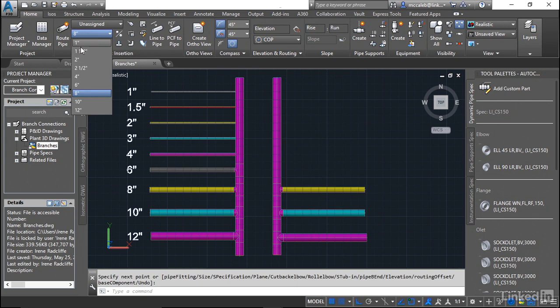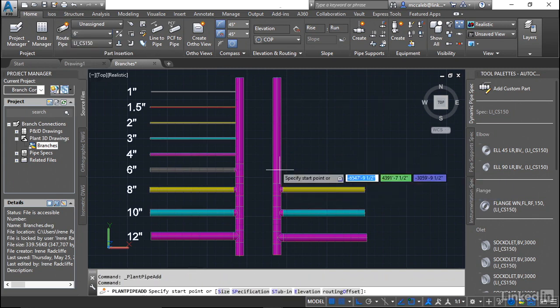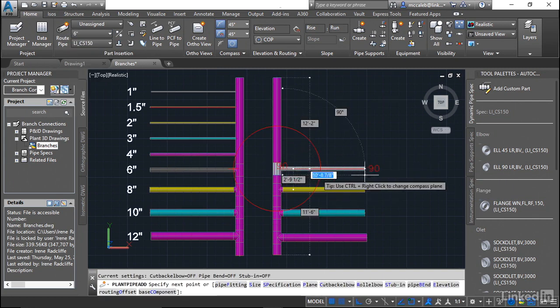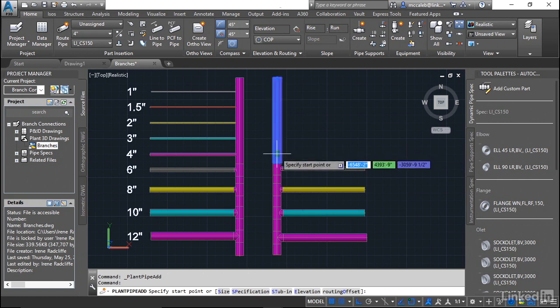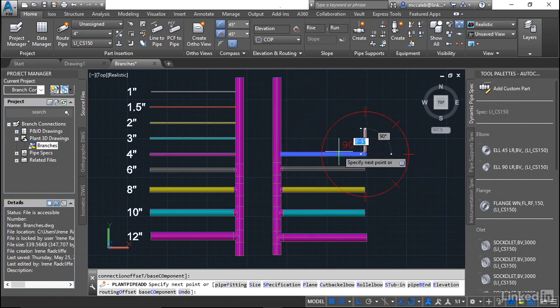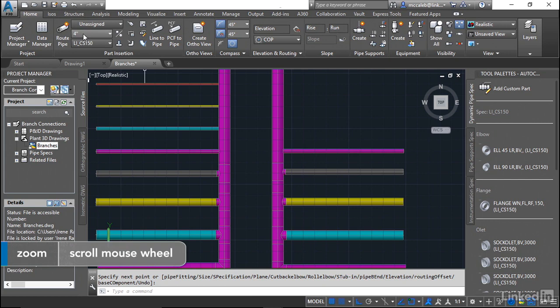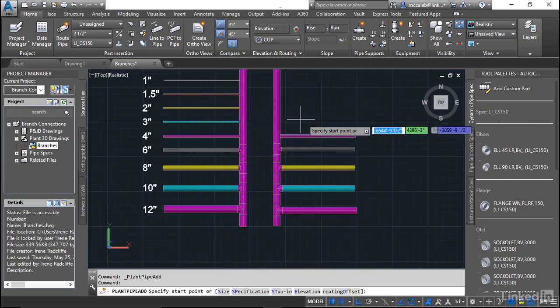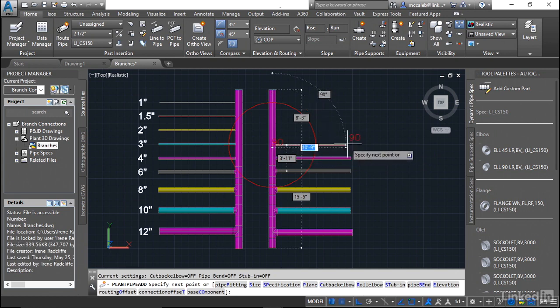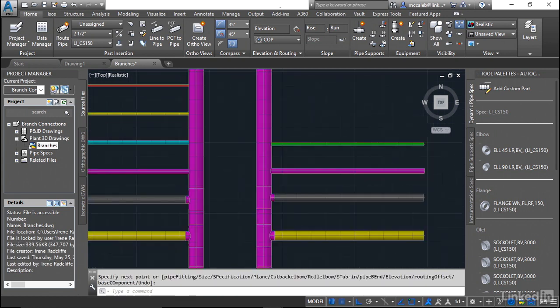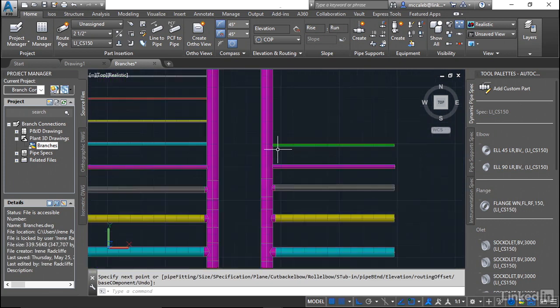Reducing T. 6-inch, reducing T, 4-inch, we're using a stub-in, so I'm going to put 2.5-inch here. In the other connection we have 3, but let's just see, because we're going to check this back against our spec. And you'll see that's a stub-in connection too.